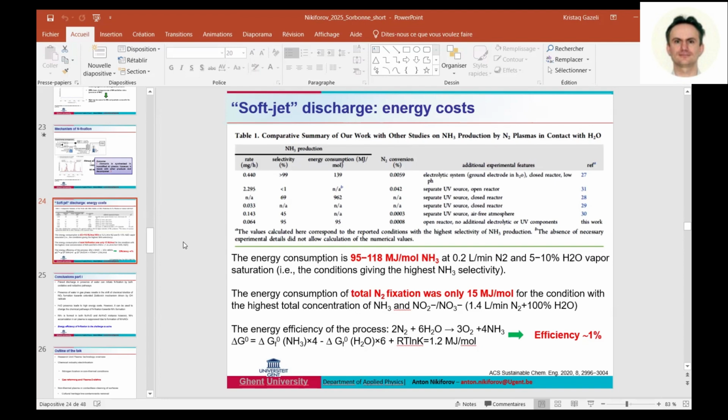Yes. Just on the last topic. In fact, a long time ago, we worked on diesel soot oxidation by plasma. We really struggled on this topic because what we found is that when you send oxygen, but also ozone, a kind of mix of oxidants, you oxidize, but with real soot, not black carbon, real soot with polyaromatic hydrocarbons, you end up forming some groups that you cannot dissolve.